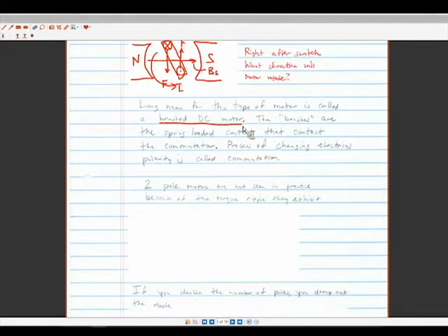Okay. So switching back to that discussion, yes? On your notes, you draw the B field of the rotor too. Is that small enough that it just doesn't affect the force? So the B field is coming from this rotor. And I think the main thing to state is that it's not going to be all that important. What we really care about in this discussion is, you have a current running through a magnetic field. What direction is the force on that coil on that certain side, and what direction is the torque?